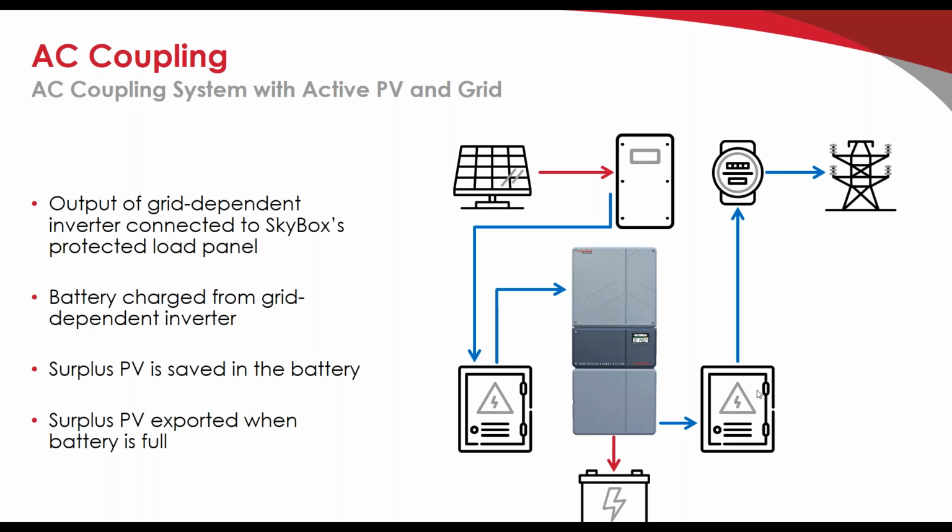Craig asks, what is 1741 SA versus 1741? I'm going to go with a layman's explanation rather than diving deep into the technical information on it, just so that I don't misspeak. 1741 SA requires ride-through and requires the inverter to adjust to changes in the grid frequency rather than simply dropping as soon as the grid frequency reaches 60.5 hertz, for example.